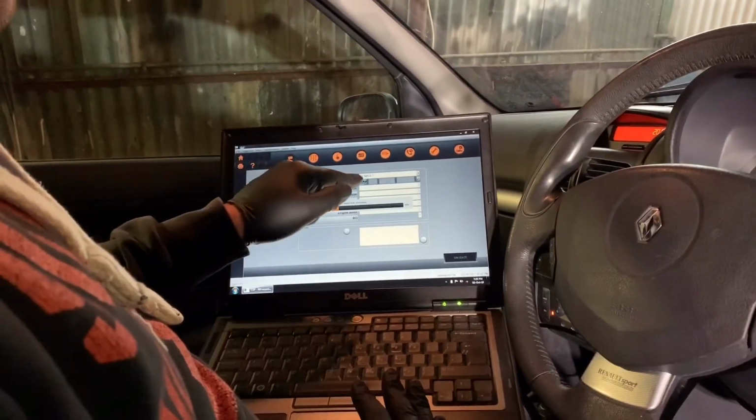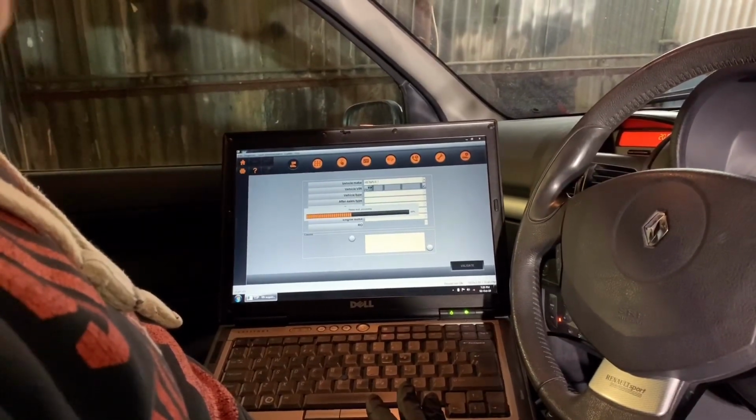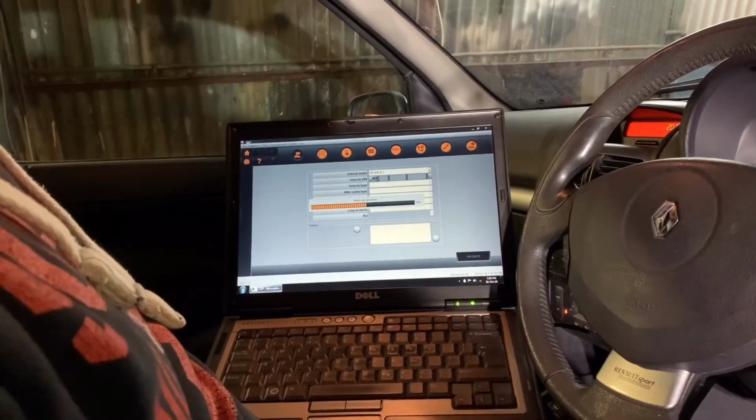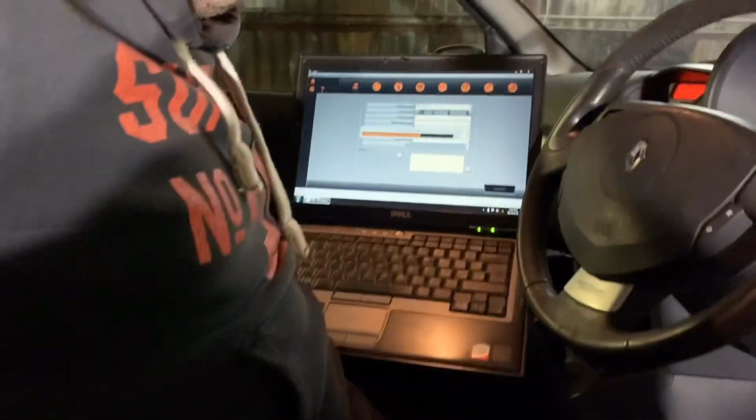So we've selected the little icon for pre-populating the VIN. Now this is something the Clip does by itself on most vehicles. Some vehicles you'll have to do it yourself, and literally if you look on the side of the vehicle, obviously we're not going to show it on this vehicle, but there's a VIN tag down there, and we would just type the VIN in.